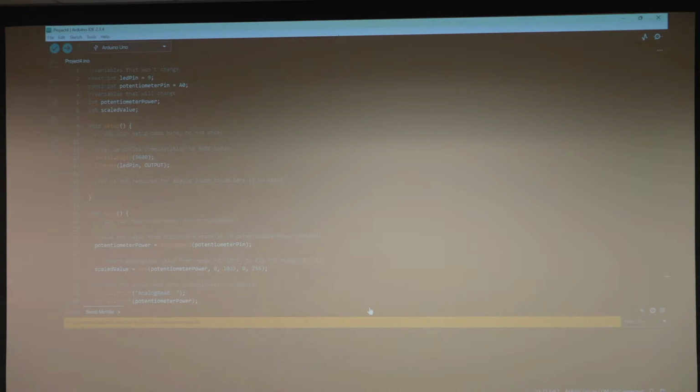So it's compiled. Yeah, so press the compile arrow, and then the arrow to upload it. I compiled it, yes, and then uploading it. Whenever you upload it, it's blinking a lot of times. So after that, what do we do next? Now you should go to serial monitor, which is that one, and then it should be endless. There you go. So try to spin it, see if it changes the values.